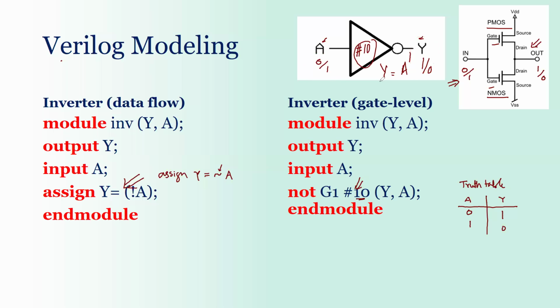That is the job of a test bench. We'll see how we write that. And then you are done with the simulation. The next step is synthesis, which will generate the gate level netlist based on this code, and accordingly your circuit will then be implemented.